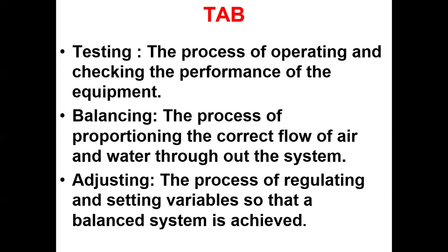That means a value in meters per second. That is the velocity. So you can simply convert the meter per second value into FPM, which is feet per minute. Once you got the velocity, now Q equal to AV. And I need to find out the Q value, isn't it? So that means area into velocity. That is the only constraint I got. So I got the velocity.